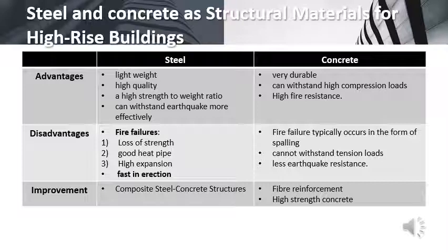The concrete advantages: very durable, can withstand high compression loads, higher fire resistance. The disadvantages: fire failure typically occurs in the form of spalling, can't withstand tension loads, less earthquake resistance. The improvement we can make is to use fiber reinforcement or to use high-strength concrete instead.